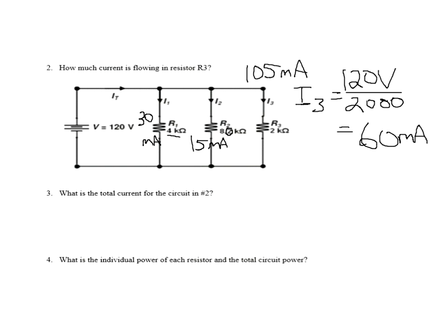But let's see exactly what it is. Let's take the total resistance here first. Do the reciprocal formula for finding resistors in parallel. So 4 reciprocal plus 8.2 reciprocal plus 2 reciprocal equals reciprocal.